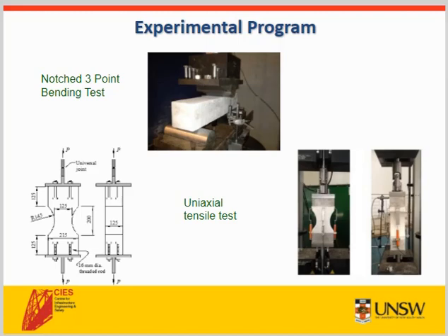The geometry of the test specimen is about 40% narrower in the midsection than at its ends, and permits failure of the sample to occur within a reasonably well-defined region. Furthermore, there are no notches in this test specimen, and so the dominant crack does not pass through a predetermined plane. To measure strain, hence crack opening displacement, transducers were placed on each of the four sides of the specimen, and these deformations were continuously recorded during testing.